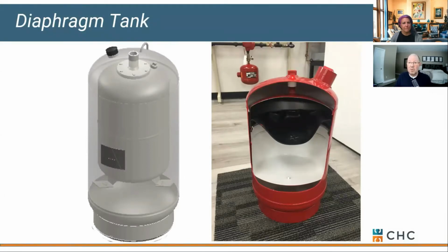But you can see this is going to be the water connection that comes in. Water's going to fill or flood this diaphragm. And on the underside here is where we have air pressure, and that's controlled off on this side. Okay, but a tank within a tank is a good way to look at a diaphragm.